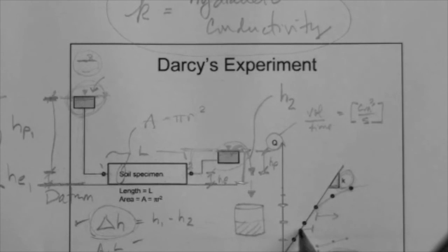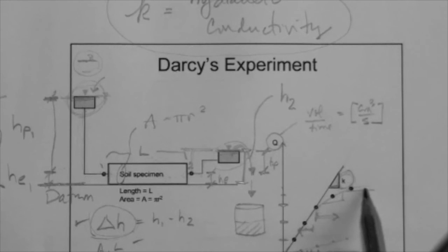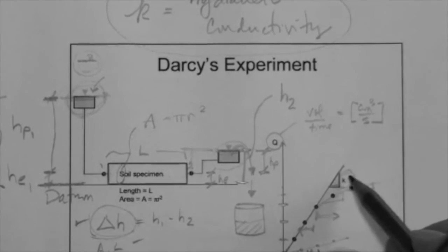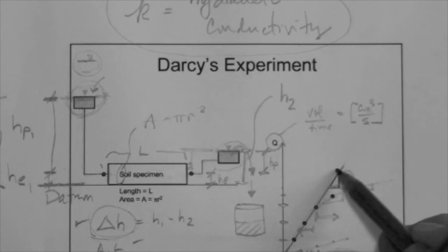When this parameter is low, the flow is laminar, which is typically the case of soil, okay? And when this parameter is high, then we have turbulent flow, in which case the conductivity is dependent on this, because you can see the slope changes at every increment of this parameter. So generally, in soil mechanics, in geotech, we're concerned with the laminar regime. That's why we adopt the K that is associated to the initial portion of the curve.